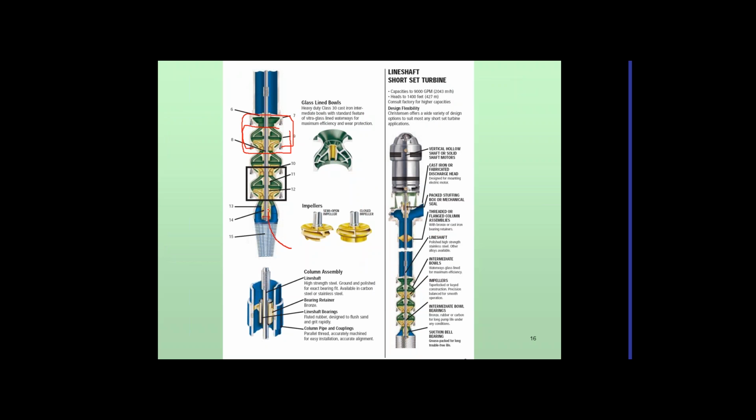So the water comes in the bottom, up through the first impeller, puts work on it. That's the input for the second bowl, and work is put on that, on up through the third one, and then it heads up to the surface through the pipe that's attached to it. And the shaft running that comes down from the surface.